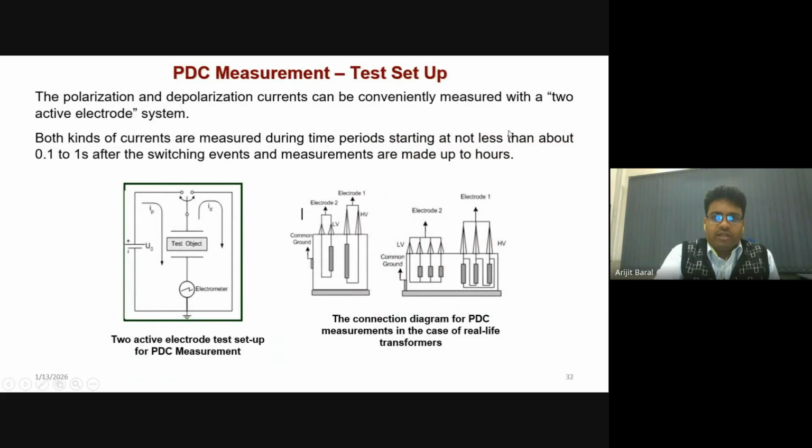Yes. If you see the middle figure, you can see the low voltage winding, shown by this gray rectangle, has two terminals. What I have done is shorted these two terminals and designated this as electrode 2. The same thing I have done with the high voltage winding.